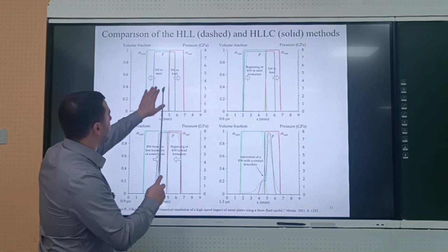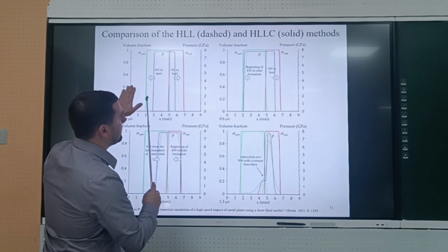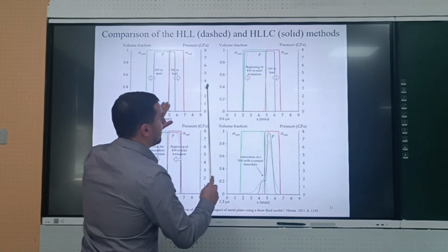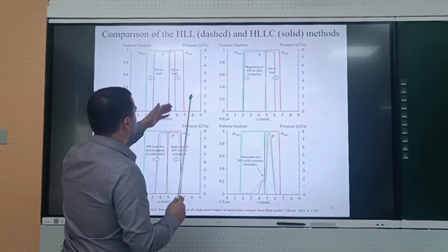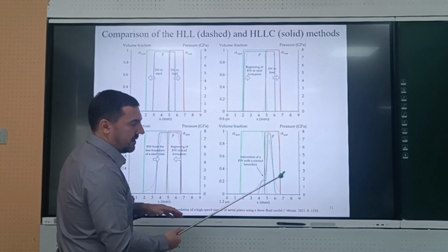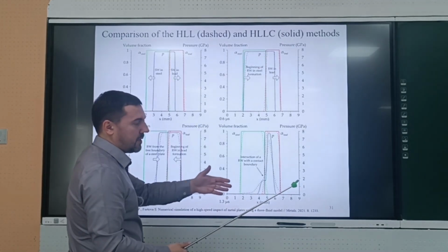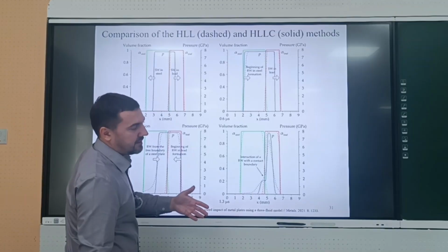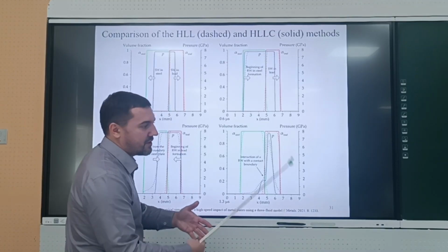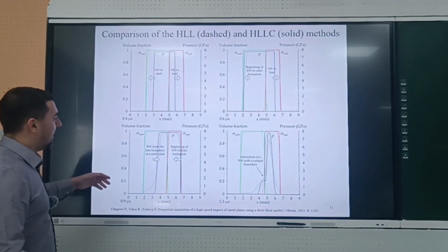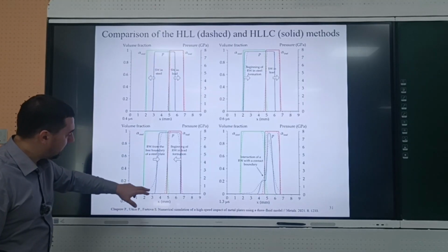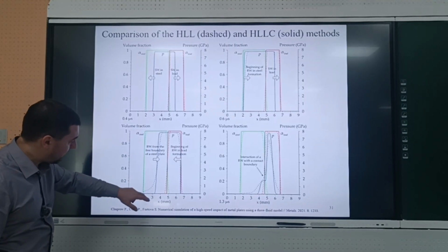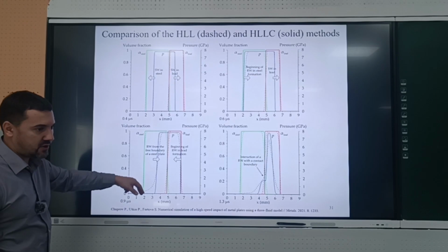Then the shock wave propagates and interacts with the free boundary of this plate, and it reflects in the form of a reflection wave. So it means that you have some compression of your material, and then the shock wave hits the free boundary, and you should get the decompression, or reflection, of your material. And it's carried out in the reflection wave. In the reflection wave, the pressure should go down to the initial pressure.